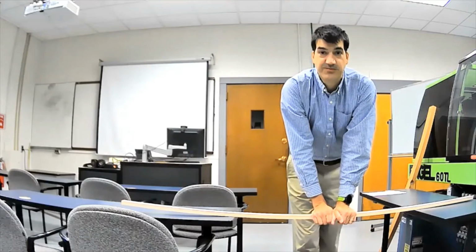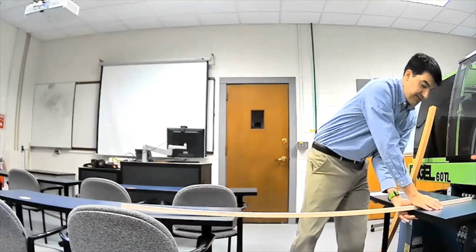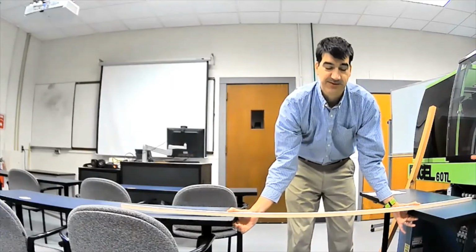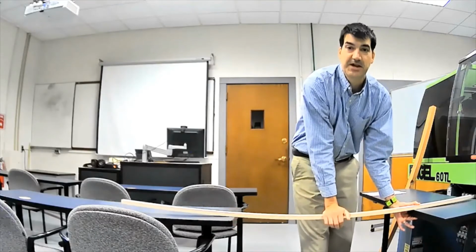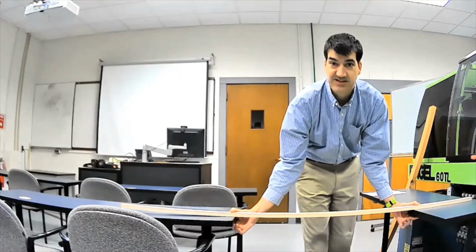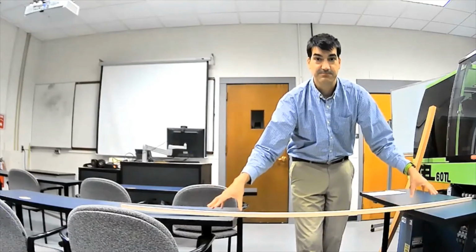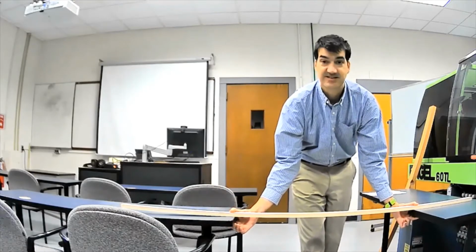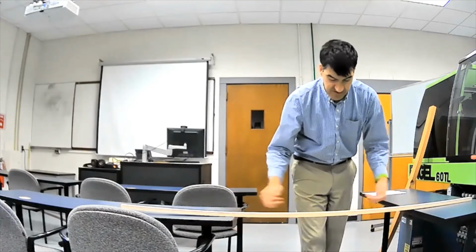Another thing I could do is I could clamp down these sides. If I had some clamps, I could clamp it down here and here. That one might not be quite as intuitive, but as it turns out, that does change the amount of force that I could apply in the middle. The beam becomes quite a bit stronger if I clamp these ends down. So it's not just resting here like a simply supported beam, but if I actually fix the sides of the beam, that actually makes it stronger. All right, so I could do that.